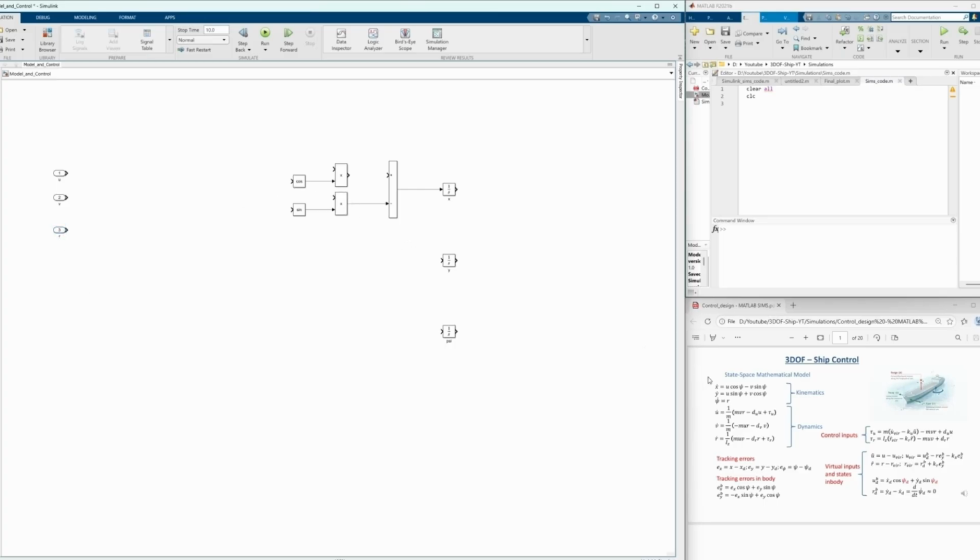So now the first one is u cos of psi. So I will simply multiply this u cos of psi. Psi is this integrator, so I will directly put it over here. The next one is minus v sine of psi. So I will take input from here, v, to this block, and then we have psi. So you can simply click over here, and this is a blue line, so we need to connect this over here. And then I have to connect this pin over here as well. So this becomes x dot is equal to u cos of psi minus v sine of psi.